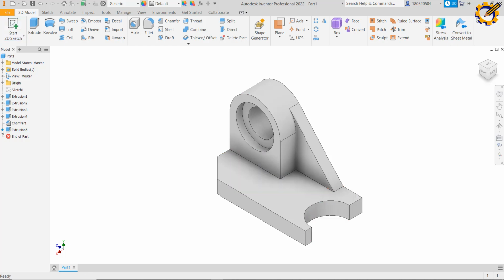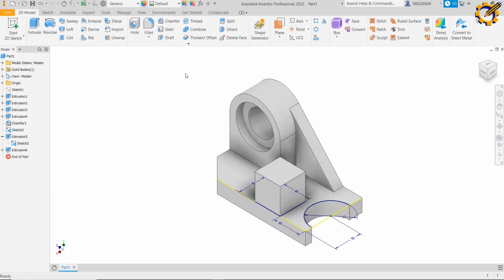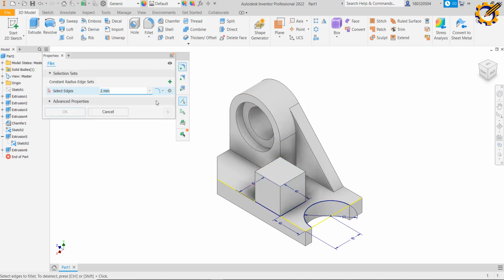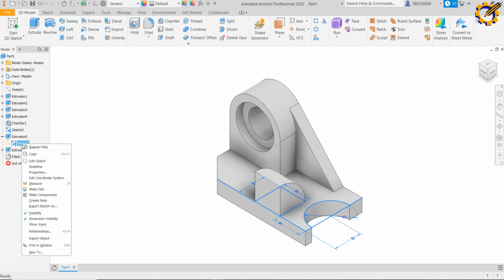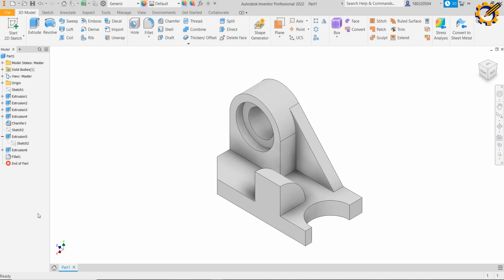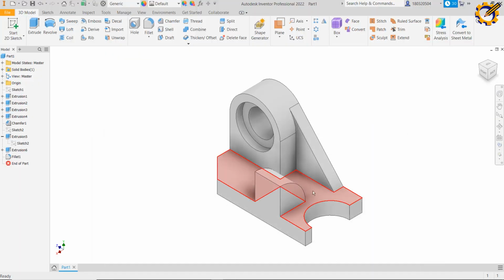Sorry, I'm going to share my sketch 2. I'm going to right click and click on share sketch. With extrude once again, clicking on this at a height of 40, then what? I'm going to pick my fillet of 40, then stand right here and click this edge. So I can now hide the visibility, and look at this. Now we have that object as displayed on the screen.